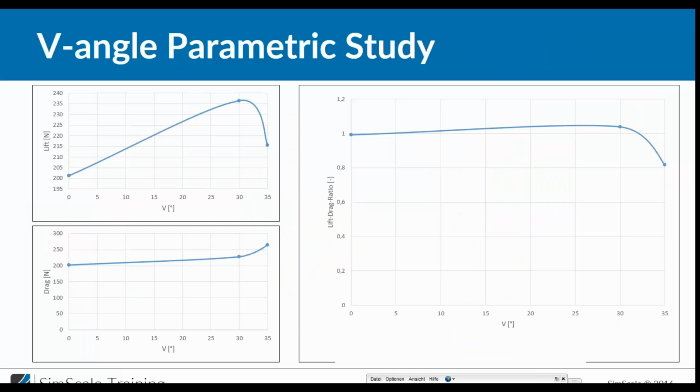Yes, definitely. And there is another parametric study we did, which is maybe much more interesting. I mean, the angle of attack was somewhat trivial, right, Akram? But there is something else called the V angle. And as you can remember, the V angle is describing the angle between the skis. And as I told you, till the late 80s, everyone was using an angle of 0. And then people found out that varying the V angle has a positive effect. And I think this also becomes clear when you take a look at these plots, right?